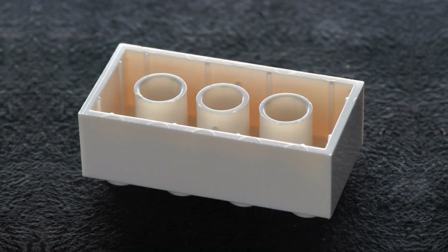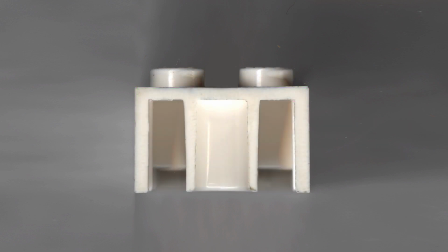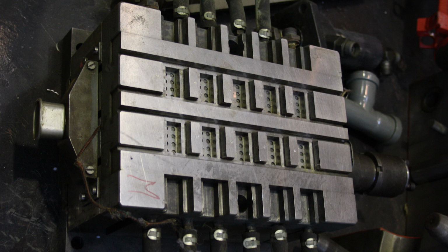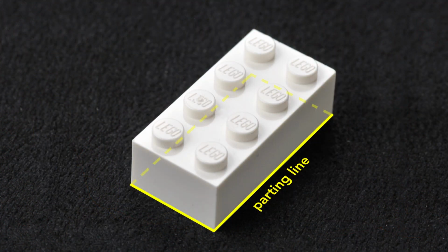On the bottom edge of the brick, you can see ejector pin witness marks. And what's most clever to me is where Lego designs their draft angle. The outside of a Lego brick must be square. So if you cut a Lego brick in half, you can see that these inner supports are thicker at the top than at the bottom. There's a draft angle of about 1.5 degrees. This helps the ejector pins push the brick off the mold. The core half and the cavity half of Lego molds are designed so that the parting line is at the bottom edge of the brick. This hides the parting line.